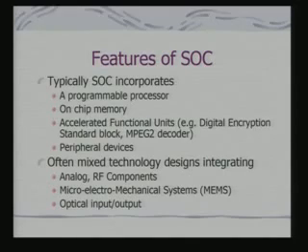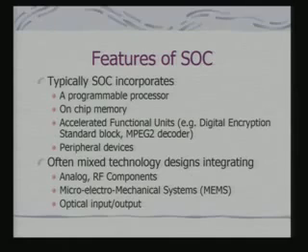What are the features of these SOCs? Typically, our SOC incorporates a programmable processor, on-chip memory, and some additional functional units which are more application specific, like a digital encryption standard block or MPEG decoder. This we call accelerated functional units. On top of that, there would be peripheral devices. But this is a very typical SOC configuration. Along with it, we may expect other components as well.